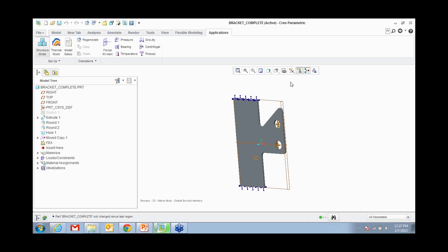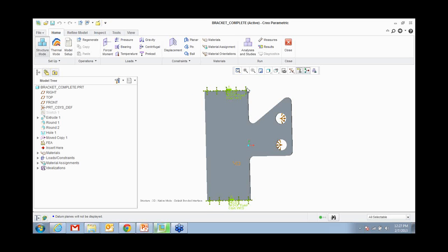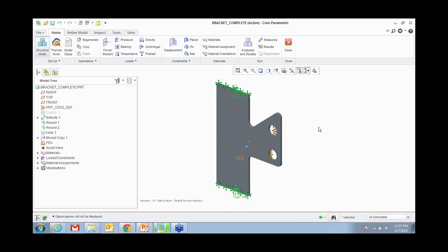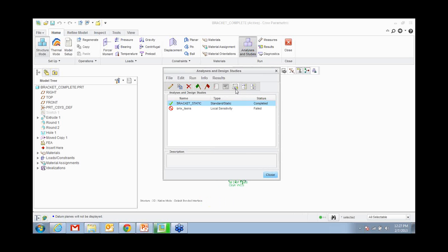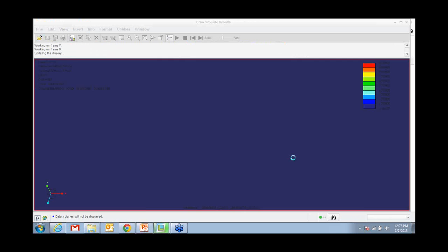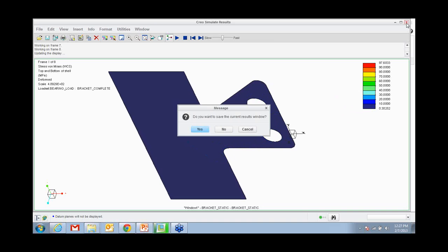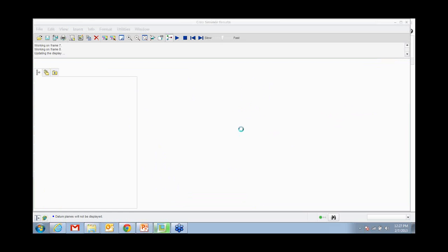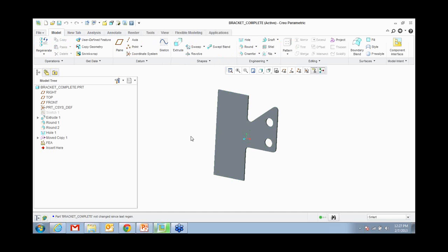and you can see that I have some bearing forces pulling and pushing from here, and I have these constraints right there that are stopping, right? So I have my analysis done, and I can go ahead and look at results. I can animate it to kind of see what's going to happen. Okay, you can also see the max stress right here at the very top is 97. Let's say my allowed value is 110, whatever. We just throw in a random number and say, hey, my allowed value is 110, so I'm allowed to make some design changes or whatever.